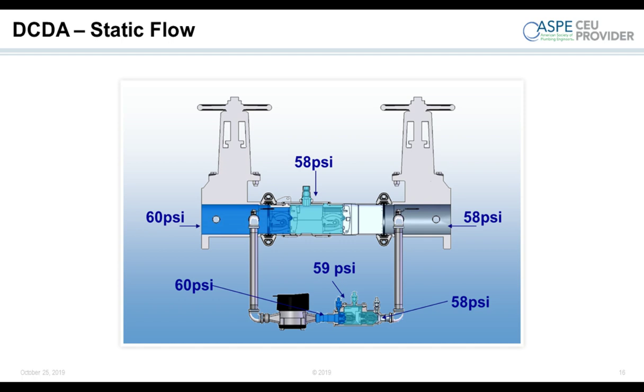Now over on the second check, it looks like there's no pressure drop across it, right? You have 58 psi on one side and 58 psi on the other. That check is not fouled. In fact, it is still a 1 psi check, but the drop across has been affected by the bypass. So if you imagine the last time water flowed through this valve, as demand dropped and downstream pressure rises, it'll hit 57 psi, which is our total static pressure drop across that first main valve, right? 2 psi and 1 psi.